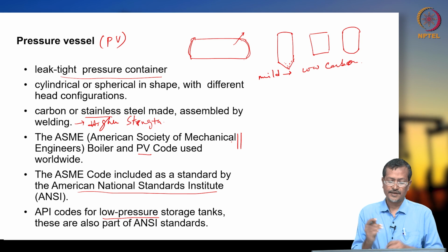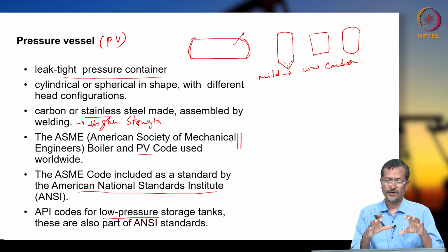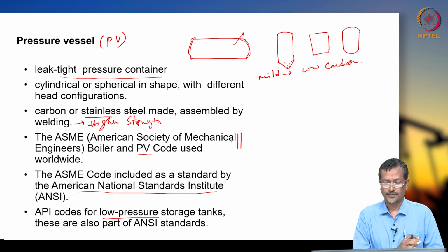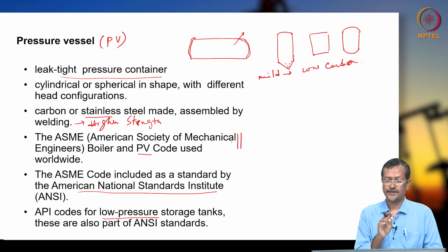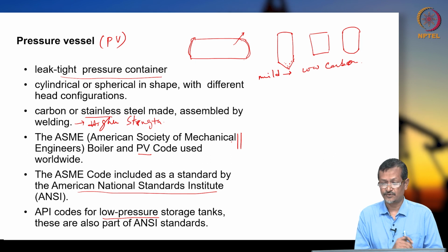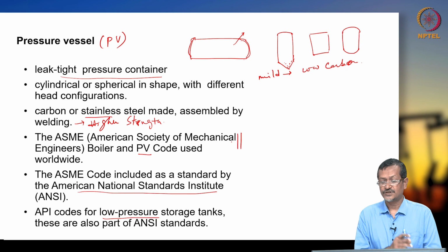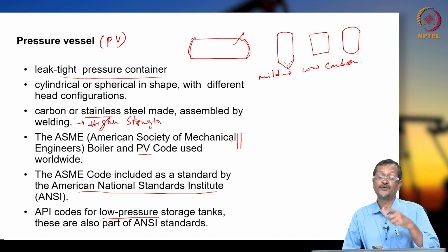Okay, so that's why for any pressure vessel, when you are buying or using it, you should know the rating of the vessel, and accordingly you use pressure. And not only the pressure rating, you have to check whether it is designed for a specific fluid. For example, H2S, I already told, carbon dioxide, or any other chemical you are handling, then you have to check what material you are using for your vessel, what fluid you are handling, and which temperature also.